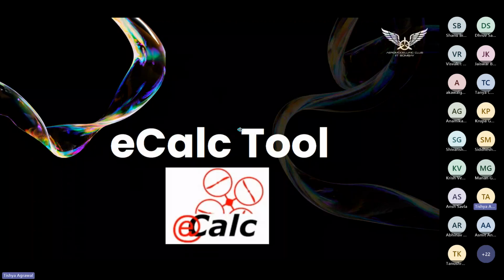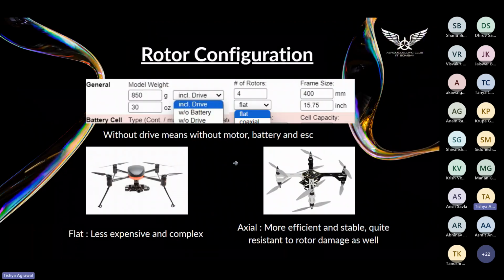The first thing we are going to discuss is the rotor configuration. In general for a drone, there are two types of rotor configurations possible. First is flat and second is axial. The flat one is the most commonly found in most drones, quadcopters and hexacopters in the market, in which only one propeller is mounted on one rotor. Whereas in the axial rotor configuration, two propellers are mounted on a single rotor and they rotate in counter directions.